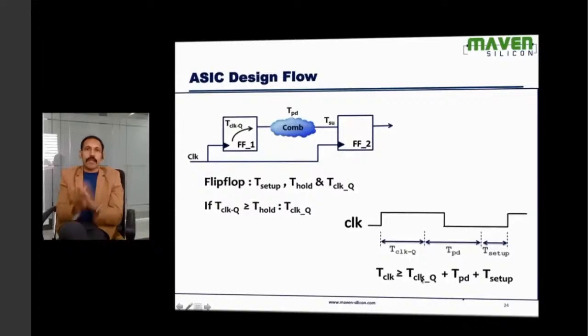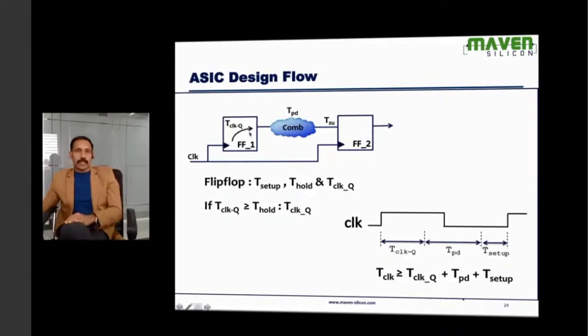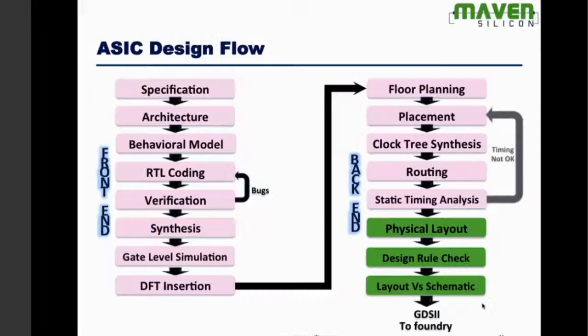If there are hundreds of levels within the chip, for every level, like register to register, this equation will be applied and all the parameters will be applied, and it will calculate, okay, this is the clock period that works fine for all the flip-flops, all the levels. And based on this clock period, the tool can confirm this is the frequency. This is the maximum possible speed.